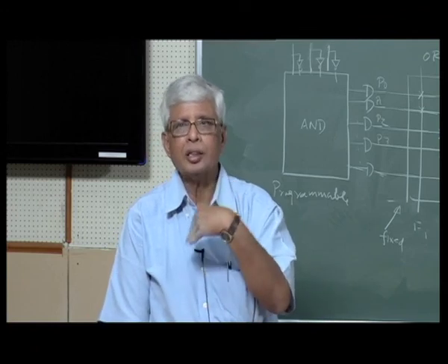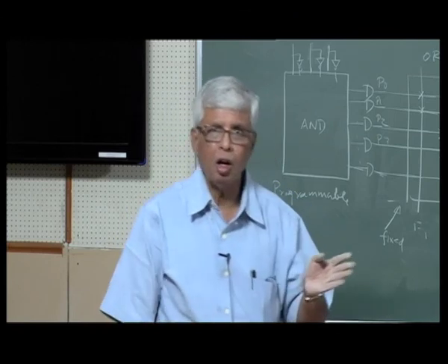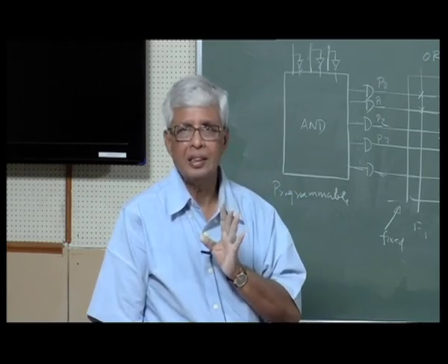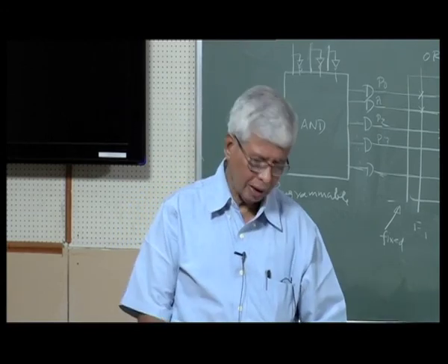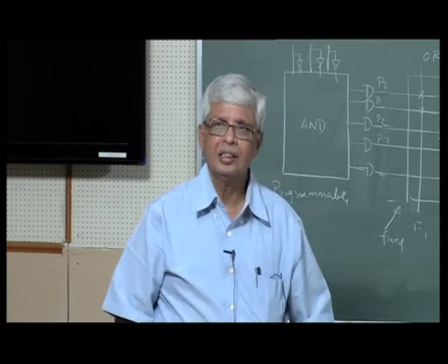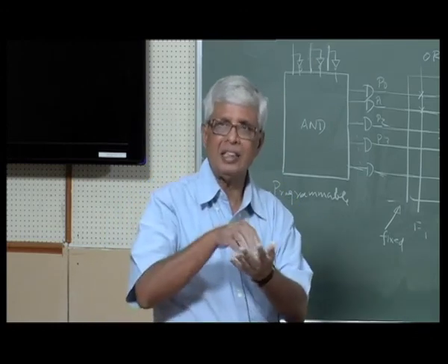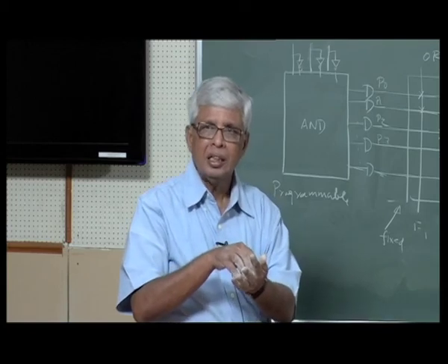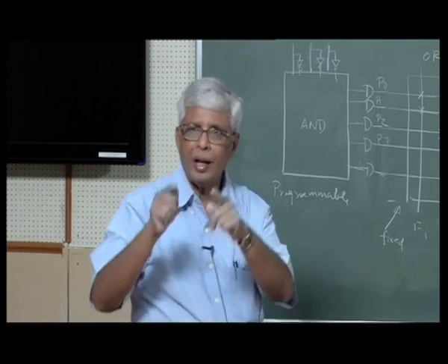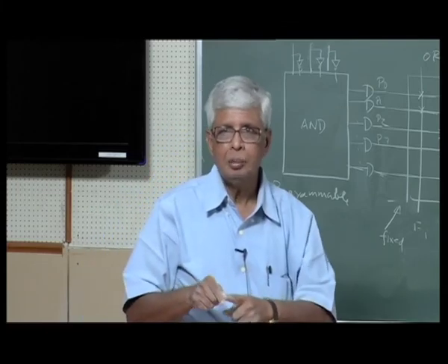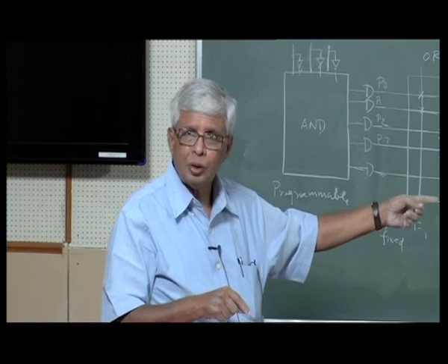ROM and RAM in computers have different purposes. But here I am using ROM as a programmable device. Instead of using gates and multiplexers and all that, which are fixed, now I have one device in which I can change things. For example, an adder, a full adder. You have to buy a full adder. But here I can use a programmable logic array, programmable array logic, to design a full adder.